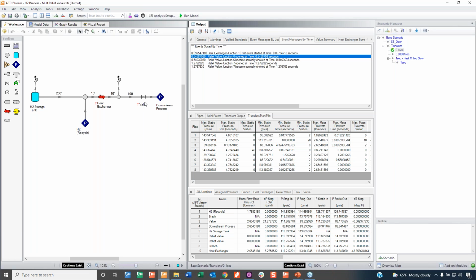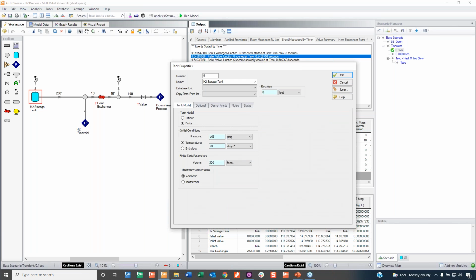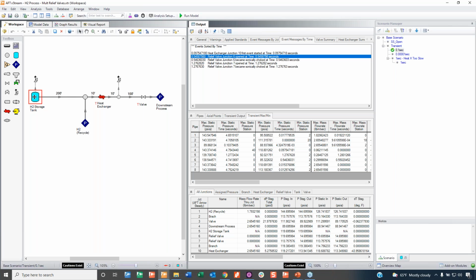If you close the valve, and that's still pretty quick, 0.1 seconds, you might expect that pressure wave to propagate through and actually trigger this relief valve first. Or maybe after some wave oscillation where it's coming back and forth, that it would trigger this one. It is actually closer to the valve than the other one. This tank, well, it being a tank with a volume, it takes time to pressurize that, right?